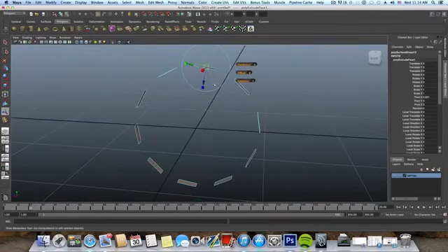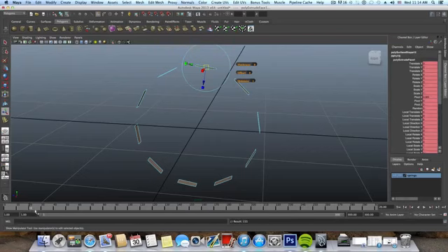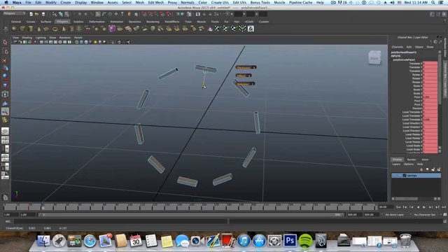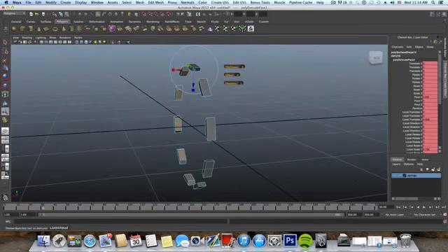So the first thing to do is on frame number 20 to press S and record this action. Now we record this, and we will switch to frame number 30. We will pull this extrusion out and at the same time scale it to something like this. Then we want to press S again to record this also.